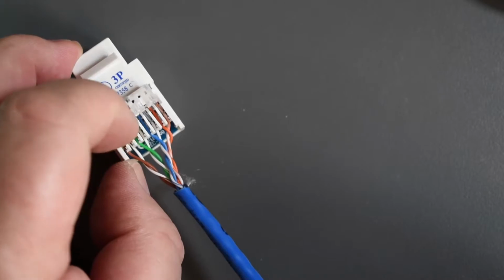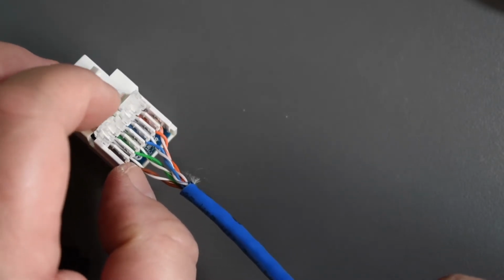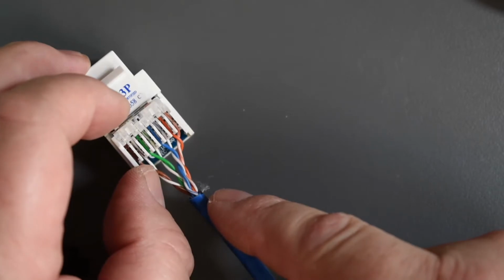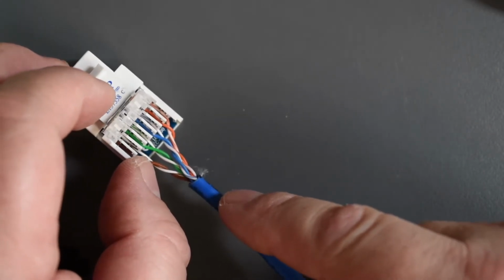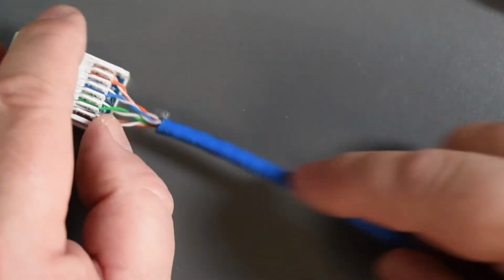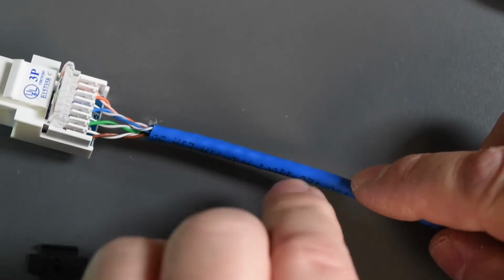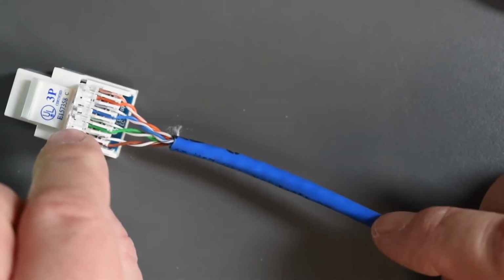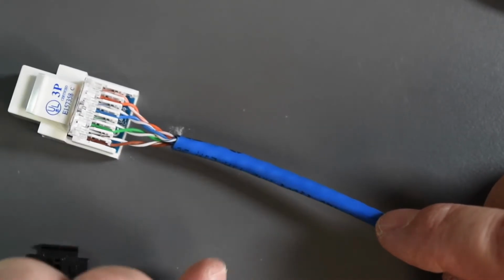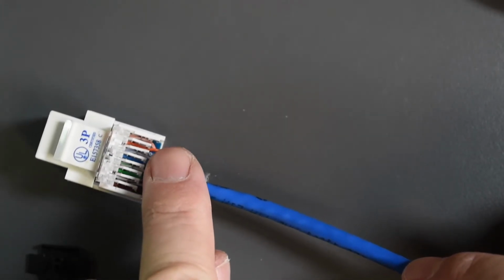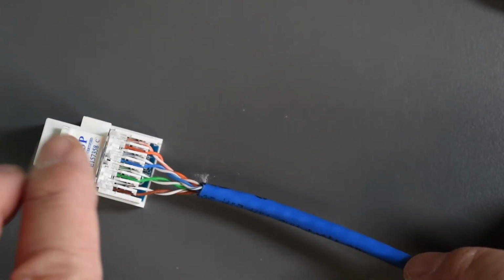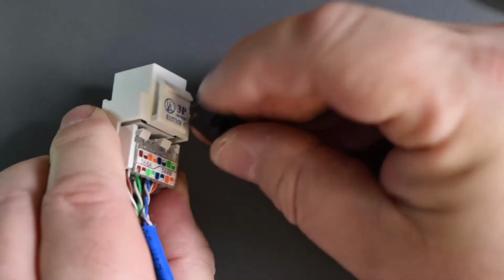That's where the twist goes. You always have to remember to keep the twist. Do not untwist the conductors. In the past, I could see some students would strip the wires about this long and then have those arranged in the grooves here, and some of them are untwisted all the way. Don't do that. Keep the twist right to the very end. It's very important. I can't say it enough. All right, so let's just apply the clip here and do the other end here.